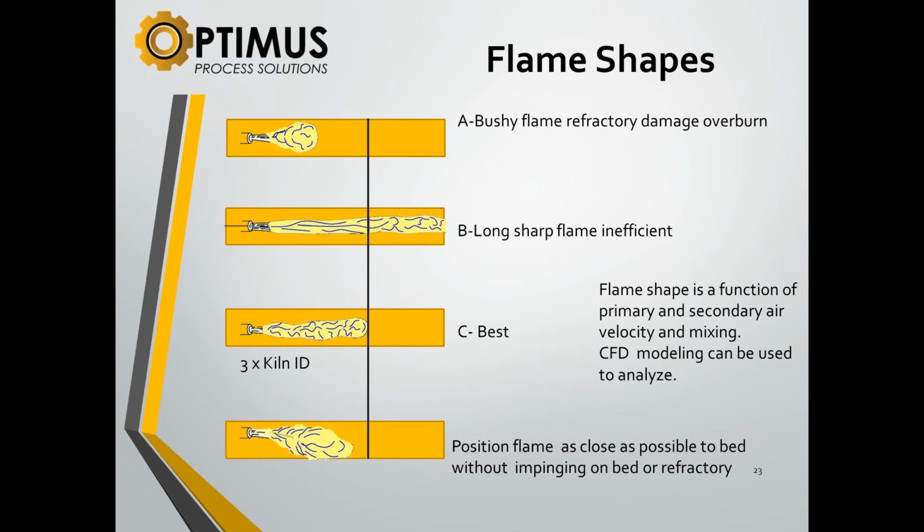Right. Okay. On the other hand, you talk to the engineer, and he said, well, let's increase that velocity. So he said, okay, and I really whipped it up. Okay, now I have too much velocity in the burner tube, and secondary air looks at it, and it's gone before I even get to it. So you get a real long flame, okay, which is very inefficient.